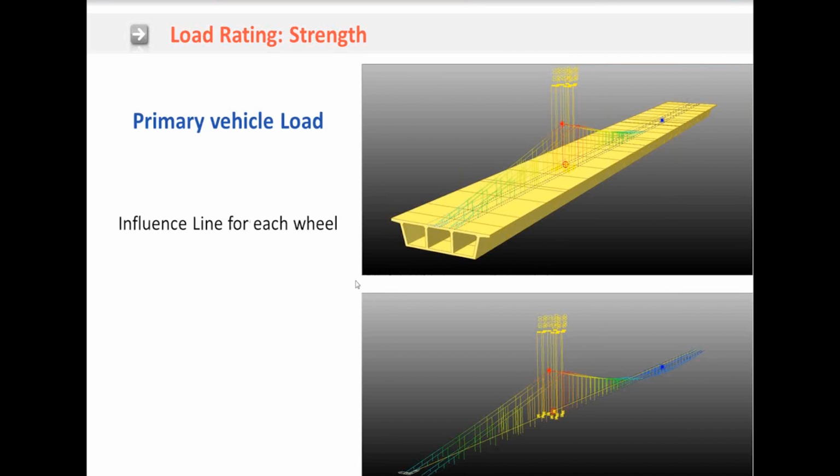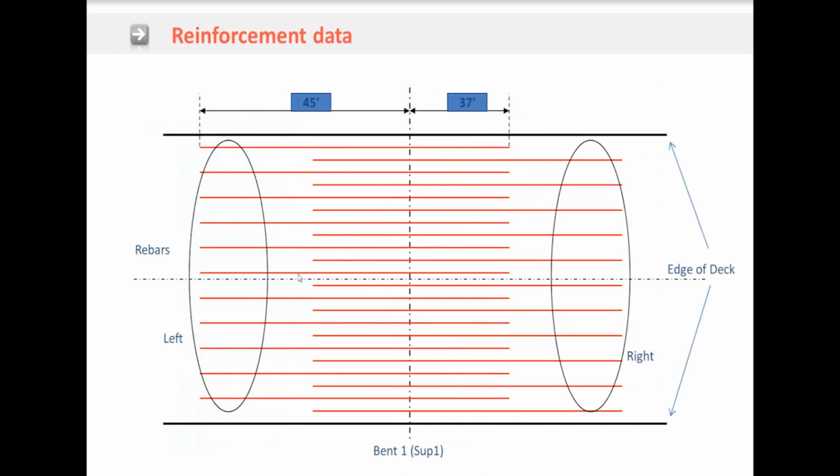Okay, so here's the thing also for the moving load analysis. It doesn't matter how many wheels you are defining or how many axles you are defining. Midas actually performs the influence lines based on all of those axles and all the wheels. So you get a pretty accurate result. It doesn't go with the assumption or summary of those things.